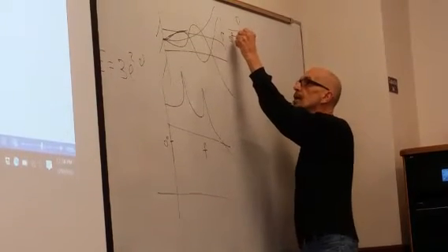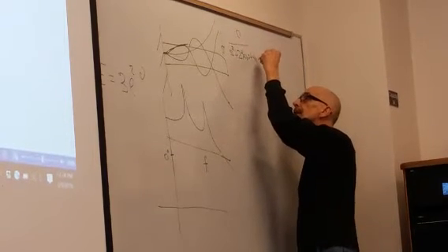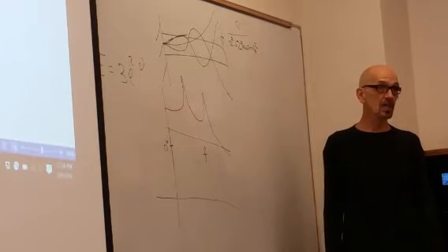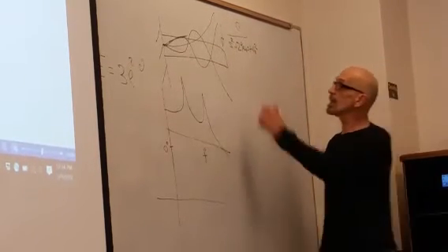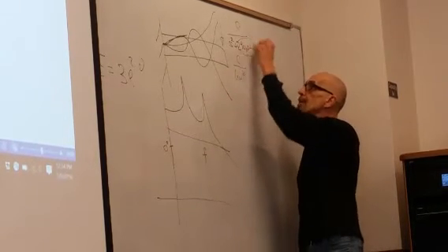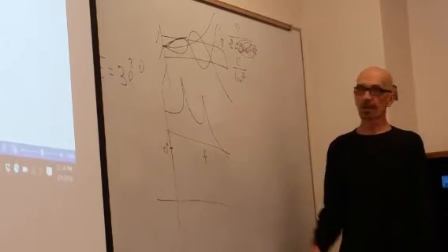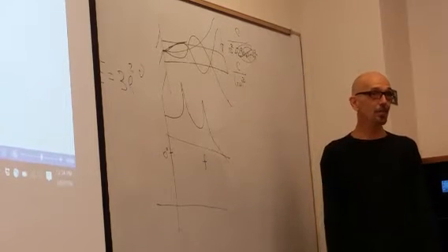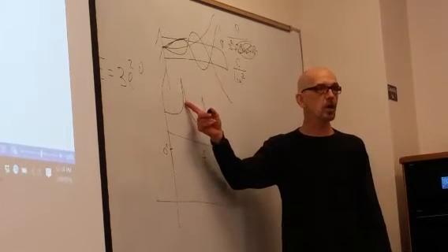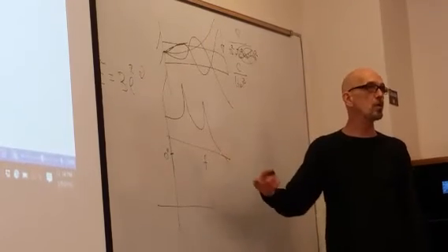C over s squared plus 2 zeta omega n s plus omega n squared. When s is i omega, and omega is huge, this thing becomes c over (i omega) squared. You throw this other stuff away. s is dominant. Now what do you get when you have this? You get negative omega squared. Well, that's 180 degrees. So this term goes from 0 to minus 180. This term goes from 0 to minus 180. So the whole thing goes from 0 to minus 360.